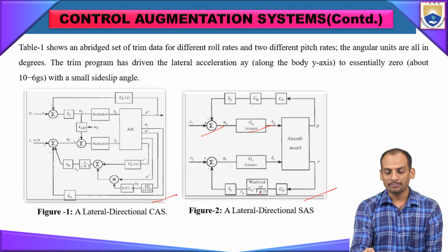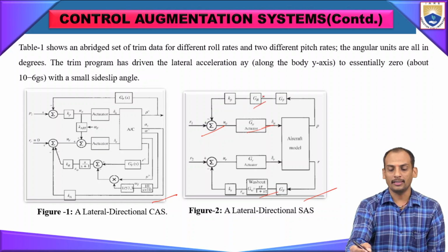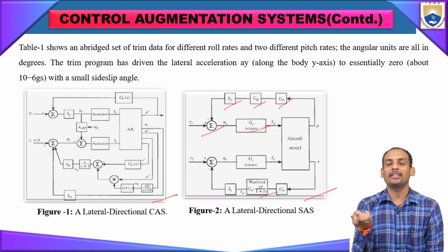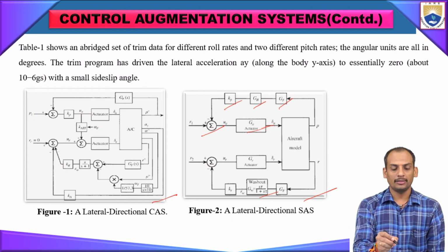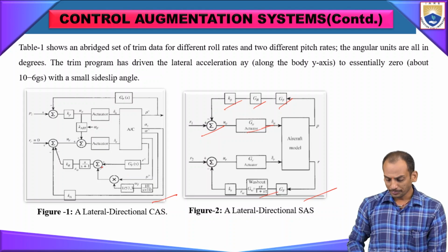In between, there are the washout transfer function, the alpha feedback, the alpha rate transfer function, the bending filters and noise filter, and the pitch rate feedback, on which we have also given some explanation. Based on that, there will be an instantaneous feedback system in between. There will be an outer loop, and the inner loop is created at the summing amplifier.